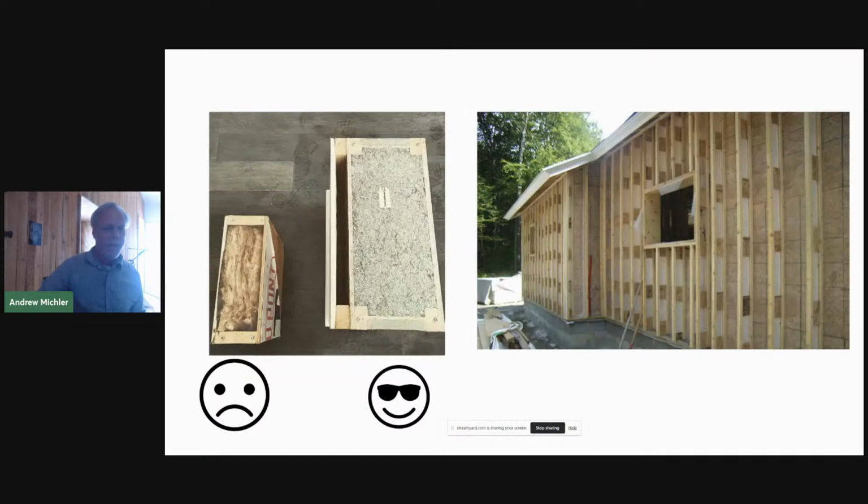And eventually, realistically, what we're looking at are really thick walls with really well installed insulation. So you've got your frowny face, which is kind of the code building, and look at that insulation, all those gaps. We don't want to see that in our buildings. And air flows through that type of material quite easily. So when we look at something called dense pack, if properly installed, it actually doesn't let air flow through it.